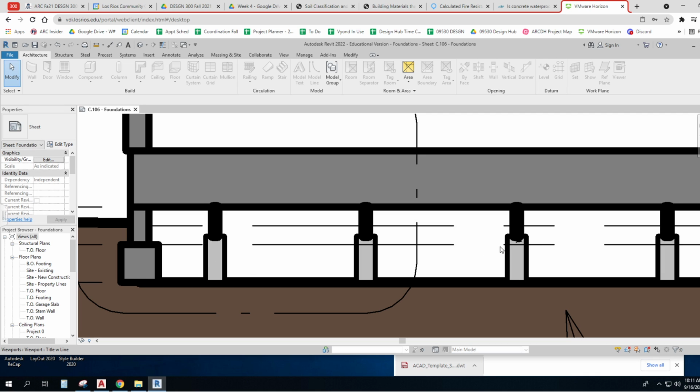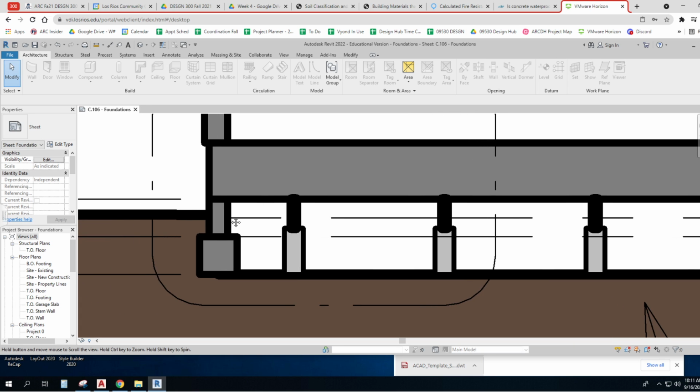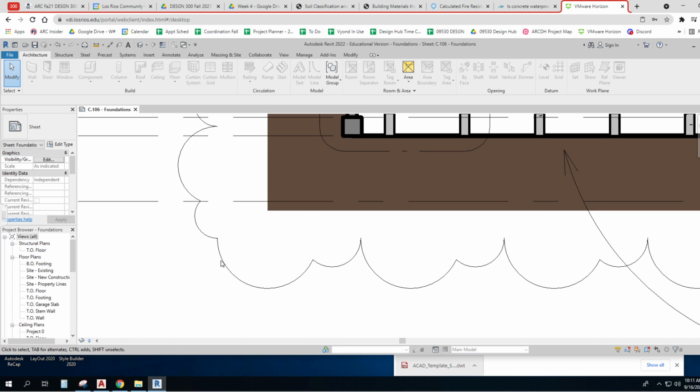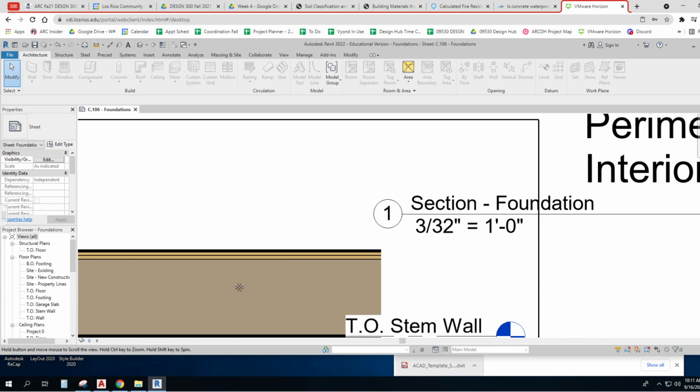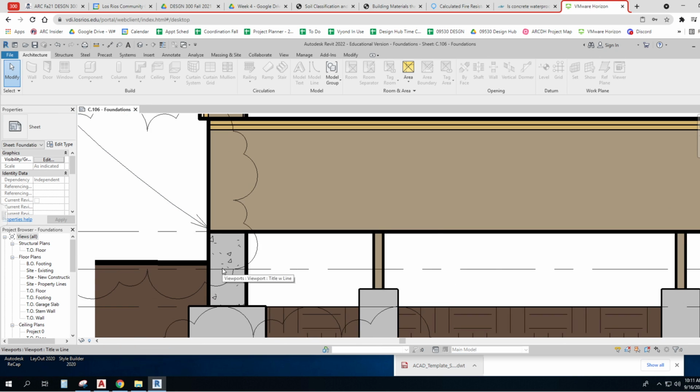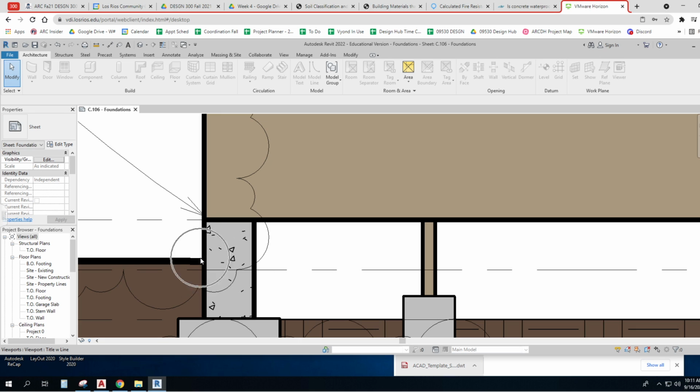And when we're talking about the foundation, pests and water are probably the two that are more likely to cause problems. And so for water, concrete is pretty good, and for pests, it's great. Now you'll see on one of these that we say it wants a 6-inch minimum between the soil and where wood starts to come into play with the flooring and the walls.